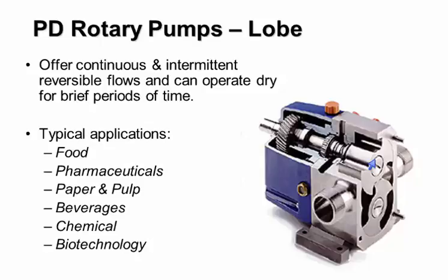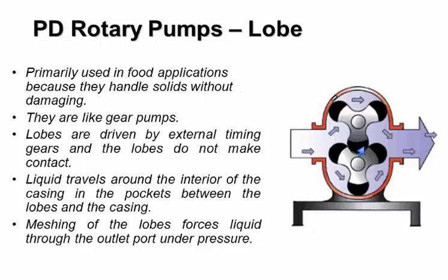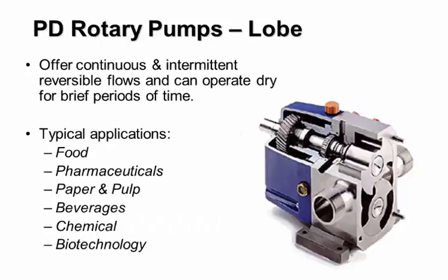Yeah, guys, you got it. I would use the non-contacting. The non-contacting one is not going to be bothered by a liquid that doesn't have good lubricating properties. I would rather use that than use the one here where I've got contact. Where I've got contact, I've got friction. So I need to use this on liquids that can, to a certain extent, lubricate between the lobes. Well done, guys.